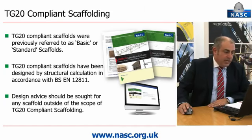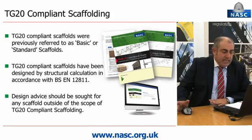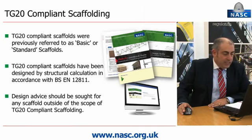TG20 Operational Guide features compliant scaffolding. TG20 compliant scaffolds were previously referred to as basic or standard scaffolds. They have been designed, as mentioned earlier, by structural calculation in accordance with the British and European standard 12811. Any scaffold that falls outside of the scope of a TG20 compliant scaffold should be designed as a bespoke scaffold.